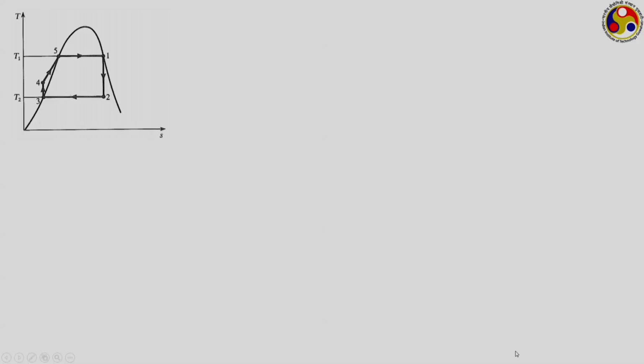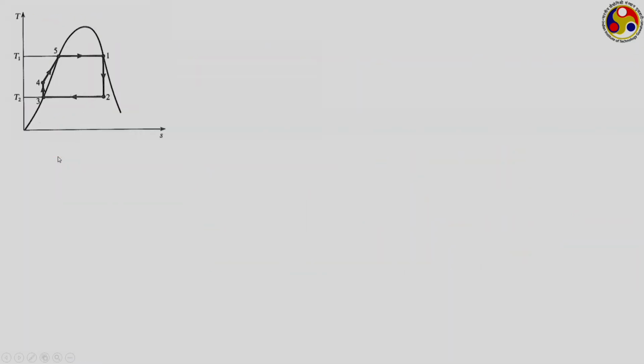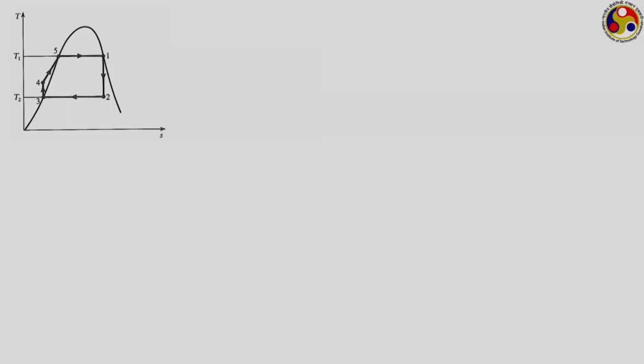So, note these numbers. Now, we shall be comparing them with an ideal Rankine cycle. This is a Rankine cycle for which we have to do the calculation. Look at this, state number 1 and 2 are the same, state 5 that is shown here is similar to this particular state. So, the states at the entry and exit of the turbine are the same, but the change is at the end of the condensation process. Here the condensation is not stopping somewhere in between, rather it is being extended up to the saturated liquid point. Of course, I have got a different diagram, so the indexing is a bit different. I am just borrowing the values from the previous problem.